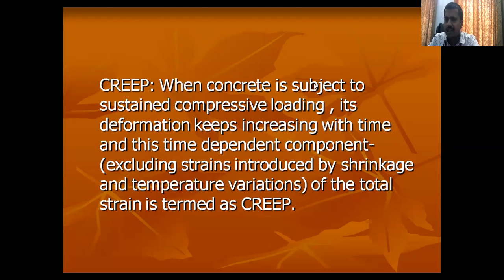I think some students are here from first year to whom I taught the basics of civil engineering. So what is the role of fine aggregate in the concrete? The very important role of the fine aggregate in the concrete is to fill the material. As you know, we mix the cement and coarse aggregate. Are they going to mix directly? Are they going to stick with each other? No, definitely not. So we have to fill some material, and that material is nothing but your fine aggregate.